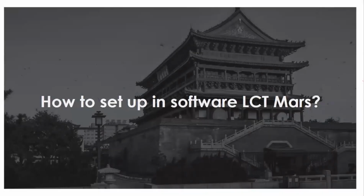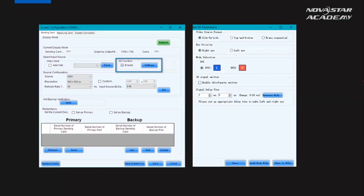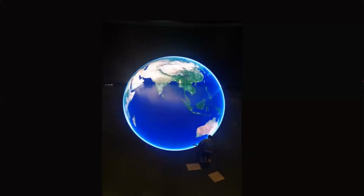So after we finish the hardware job, let's see, we have already set up the hardware: the emitter, the controller, and the 3D glasses. And we have already finished the DVI mapping between the splicer and the 3D controller. So how do we set up the 3D function in our software? We need to run our Nova LCT software, head into the sending card page, and enable the 3D function. We need to select the video source format, and also the eye priority. It's not difficult to set. And after the software setting is done, then bingo, everything is set. Finally, the project finishes with a 3D display effect.